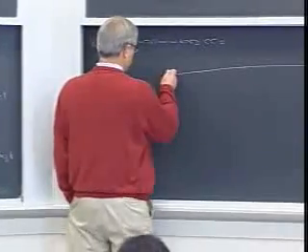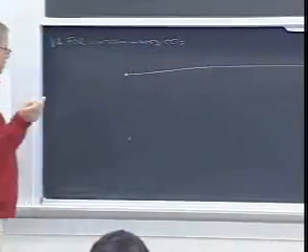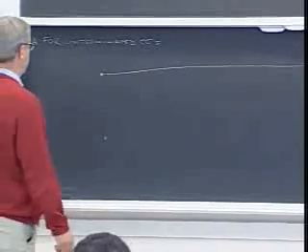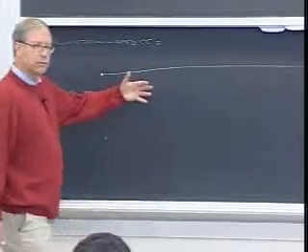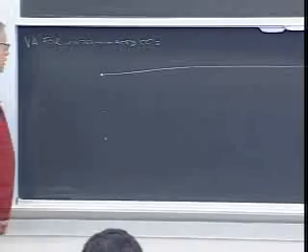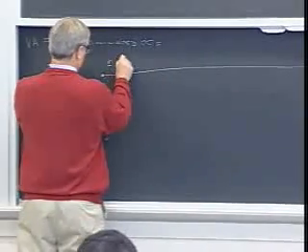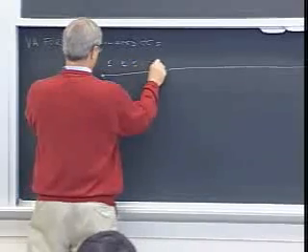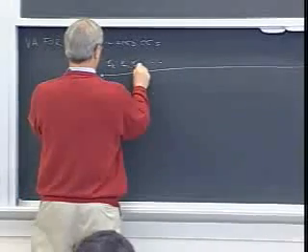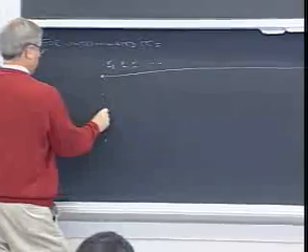Basically, you're in one of 4 states, or 2 to the nu states. You don't know which one. Let's just give them all cost 0 and start decoding using the 4-state trellis. And we just start receiving 2-tuples from here on. We get r_k plus 1, and so forth. So how should we start? Well, we'll just start like that.